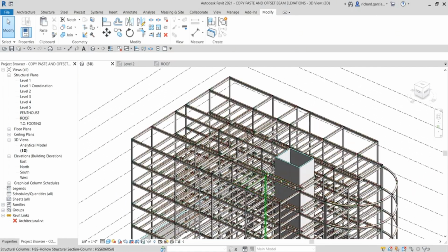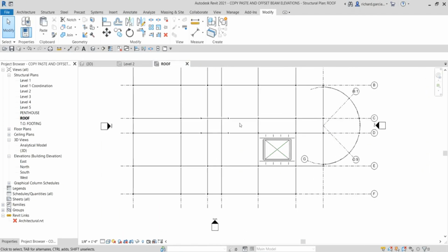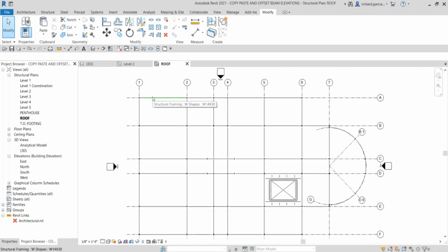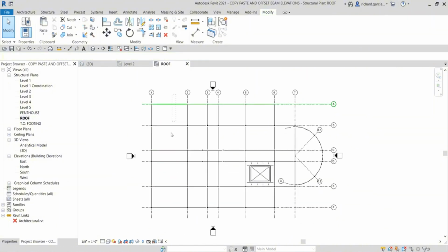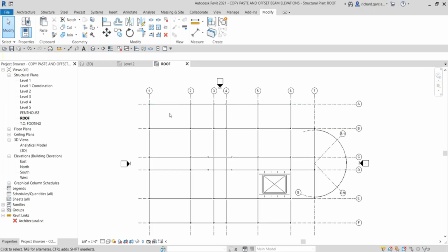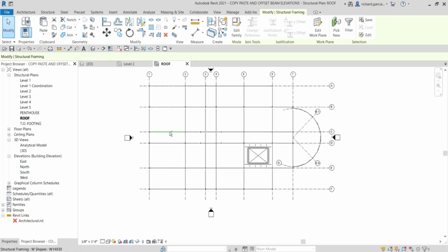So what we are going to do now is offset our beams, our horizontal beams. Okay, let's say 2.5. To do that, let's select one horizontal and then hold control. Let's use that one. I think I can also use crossing. No, don't use crossing. So just use manual. Click, hold control, select all the horizontal elements.